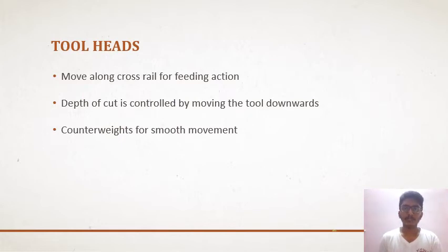The workpiece during the machining operation will have to remain fixed to the table. Since heavy cuts are made in planing, the cutting forces are also large and the workpiece should not be shifted due to these forces. Most of the time, complex workpieces will be machined, so the setting up process requires heavy duty T-bolts and clamps.